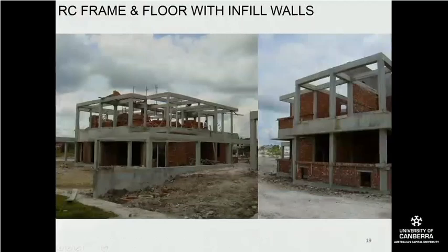These were some duplex houses that I did in Malaysia in the 1990s. And what you can see there is that this concrete structure is actually holding up the roof, and these brick walls actually sit inside the concrete frame. They are infill walls which don't have any function in holding the thing up, but it gives you a nice solid feel nonetheless.